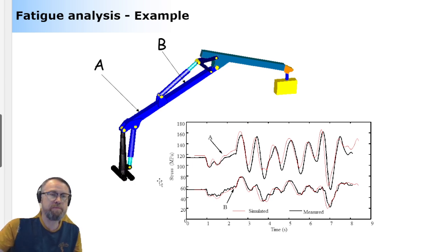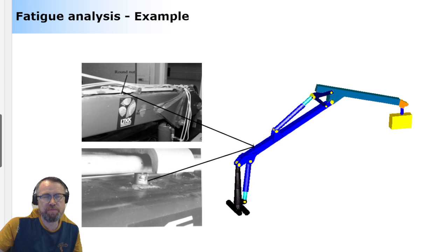All right, so finally, once having this information, we were able to make a fatigue life prediction. And this particular design wasn't a very great design. Here's the reason. There are hydraulic pipes that go to this telescope cylinder here, and these pipes were connected to the upper part of this boom by using small welded nuts.